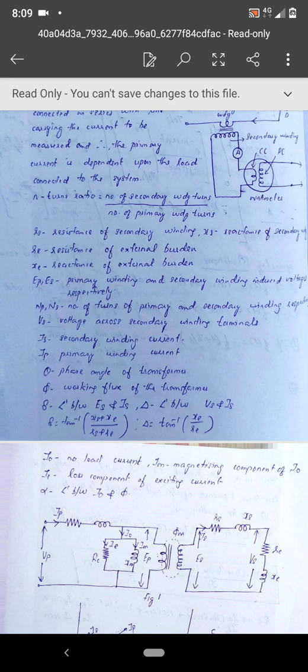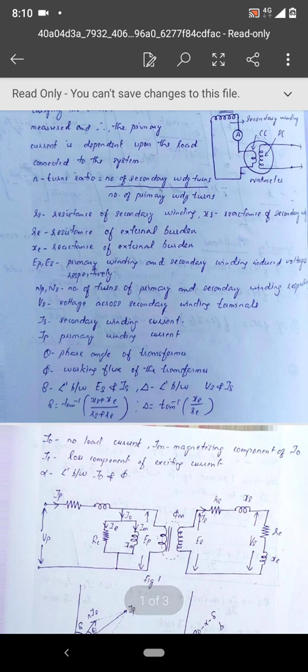So you cannot measure 100 amps straight away using a conventional ammeter, but you can measure it with an instrument transformer where that 100 amps is converted to 5 amps. So seeing 5 amps in the secondary circuit, you can know that it is equal to 100 amps in the primary circuit.